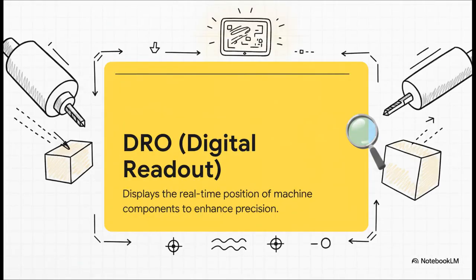While all of this cutting and rapid traversing is happening, the operator is constantly monitoring the DRO, or digital readout. Picture a glowing screen of numbers right next to the machine. These numbers show the exact real-time physical position of the machine's components, like the spindle or the tool. The DRO is there to enhance precision. It guides the operator's eye, proving in real time that the physical tool is standing at the exact coordinates the part program dictated. It bridges that final gap between the digital instructions and the physical reality of our bracket.